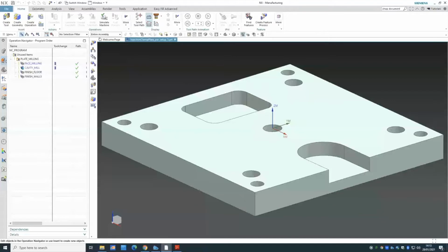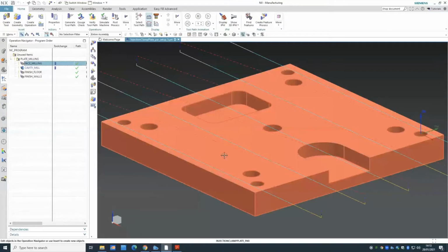Great. So what we're going to do today, as I mentioned earlier: we've already done the face milling. You can see that was the face milling we've done, the process on the top of the plate. We've done it as a face milling finishing, but of course, if you want a cleaner look, you can always have a roughing, which removes more material, and then do a slow finishing on top, which we can do with the face milling.